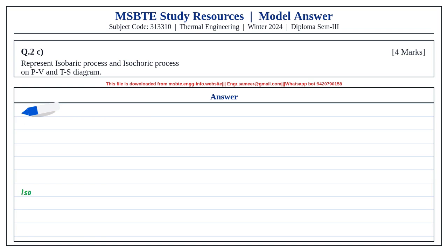In working, exhaust steam enters the shell and passes over the outside of tubes. Cooling water flows through the tubes. Steam gives heat to the cooling water and condenses. The condensate is removed by extraction pump.